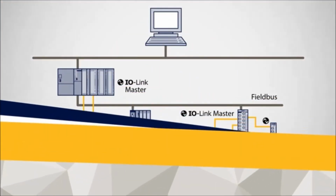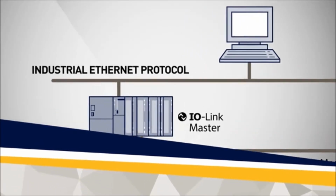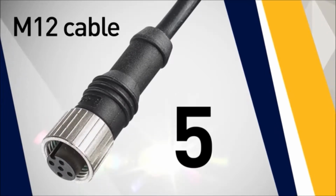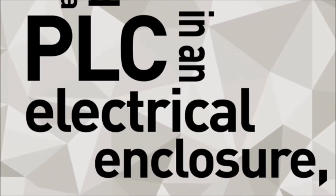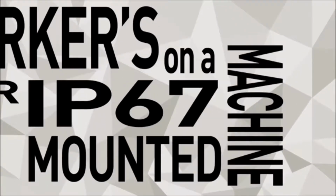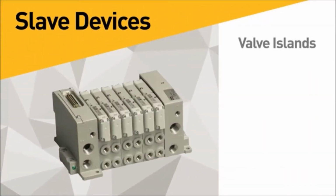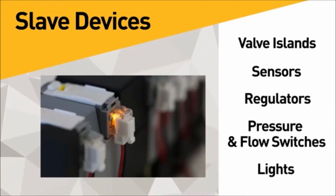It is an open protocol which can connect directly into an industrial Ethernet protocol such as Ethernet IP or Profinet, using standard versus proprietary cables. I/O Link uses standard non-shielded M12 cables with 3, 4, or 5 wires. I/O Link masters can be IP20, connected to a PLC and mounted in an electrical enclosure, IP65 like Parker's, or IP67 mounted on a machine. Master devices include PLC masters or I/O Link M12 or M8 I/O blocks. Slave devices include pneumatic valve islands, sensors, regulators, pressure and flow switches, lights, and several others.